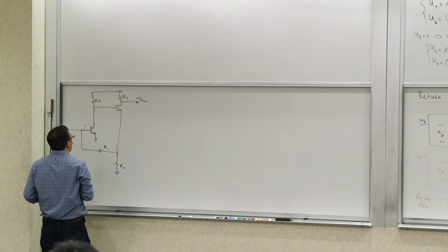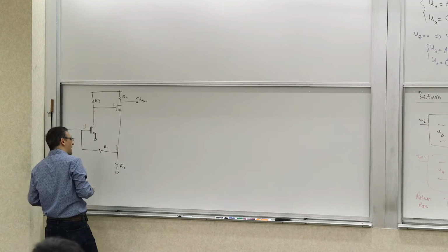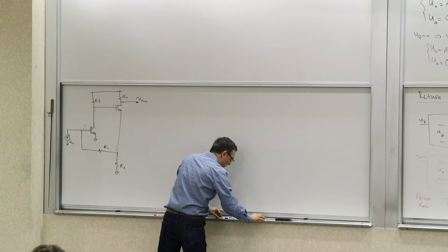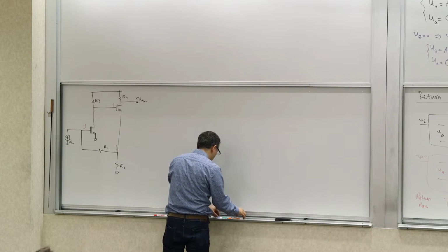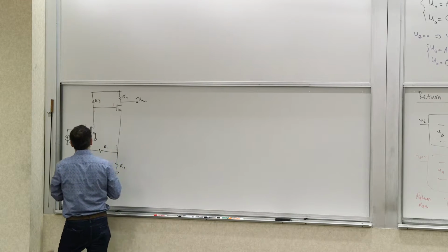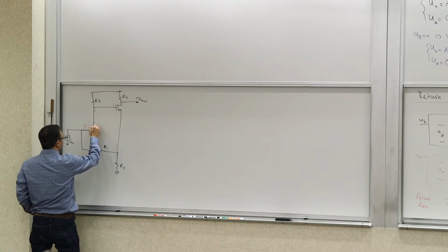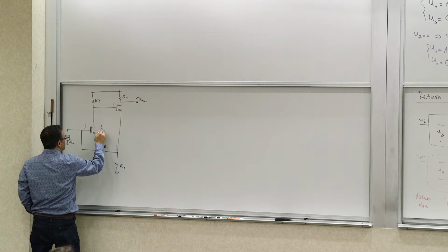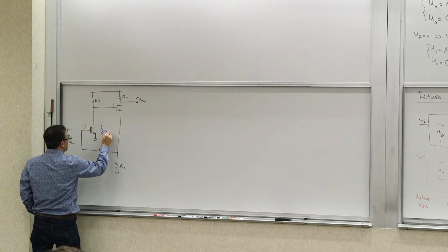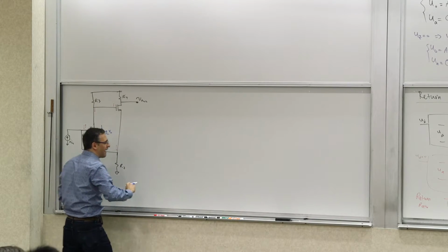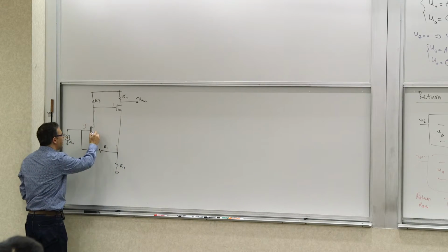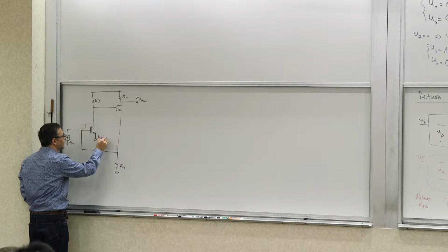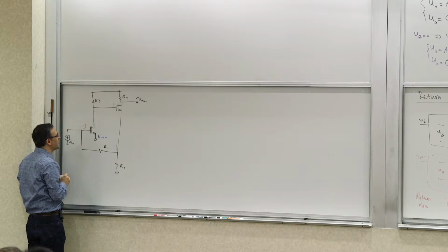And now that we know that the feedback is negative, we can apply the asymptotic transfer function formula. To do that, let's calculate several different parameters. So first, we did this before, but we will do it quickly. So let's say this is the source of interest. So we are thinking about this as really a pi model. So this is a gm v pi here, right? So we have a gm v pi, and we want to calculate K going to infinity here. So if we make that K infinity, what do we get?